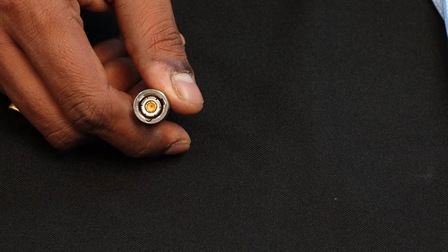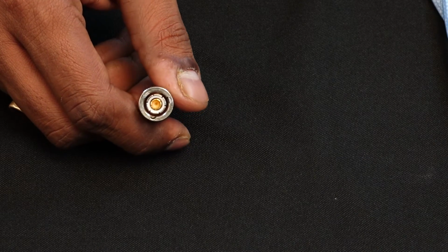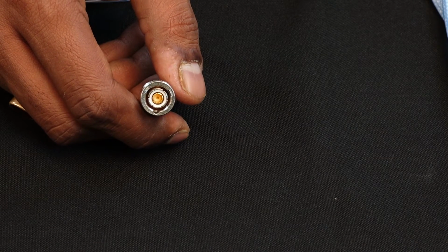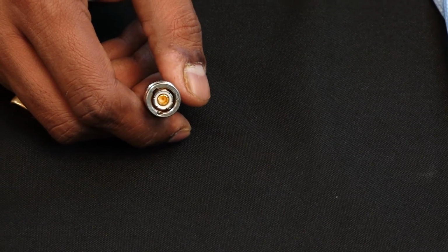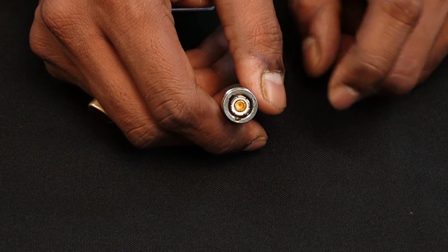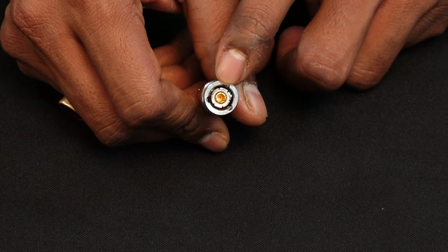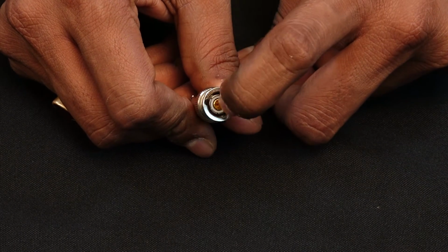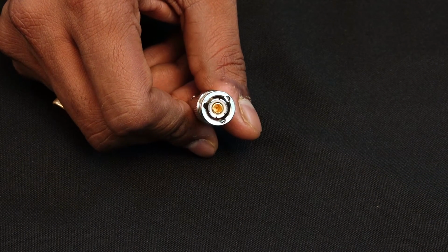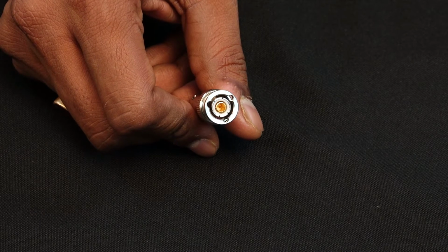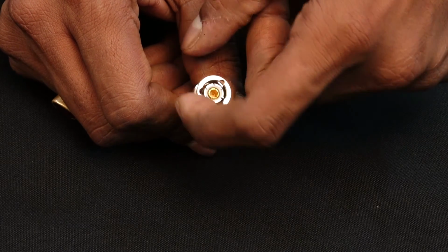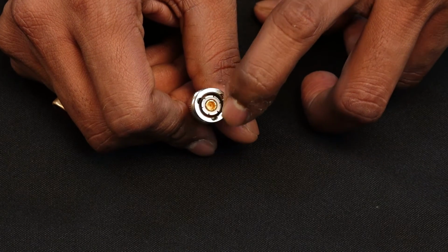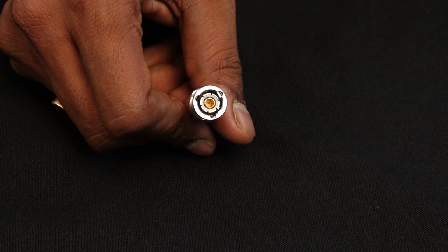The fourth component that I'm showing you here is called a tri-X connector. The reason that I'm calling it a tri-X is because it has three different signal carrying capacities. The first pin that you see here on the inside is called a signal pin. The second outer shielding here is called a guard ring. The guard ring is important because it protects your signal from any external noise. And the third outer shielding is a ground signal. So basically you have a signal, you have a protection guard ring, and then you have an outer ground as well.